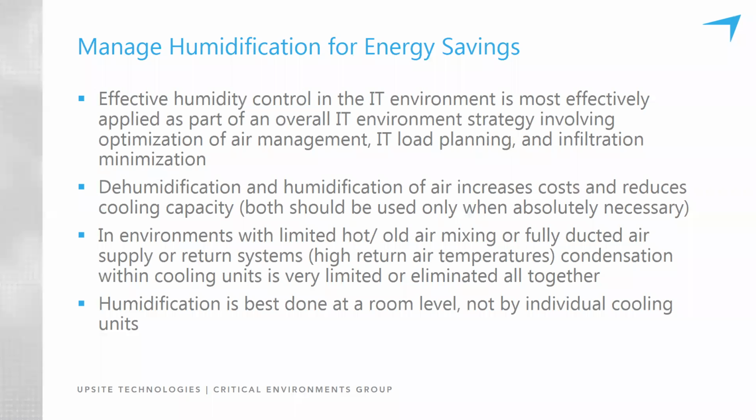Either that way, or with cooling units that are talking to each other and know what each other are doing. Because as many of you have probably heard, cooling units can fight each other. One cooling unit can be trying to provide humidification, and right next to it is a cooling unit that is attempting to dehumidify the air. And this consumes a great deal of energy.